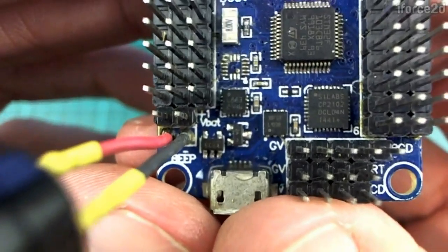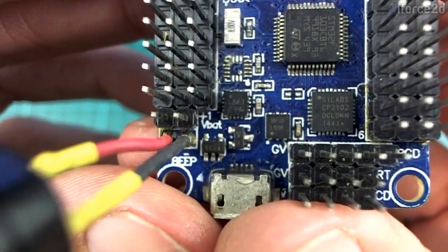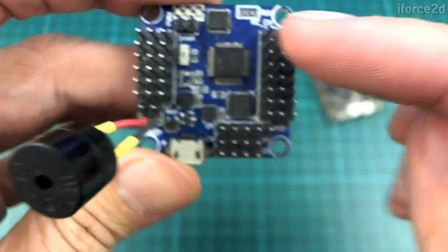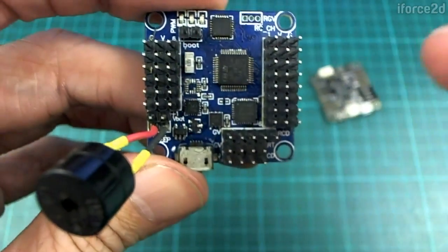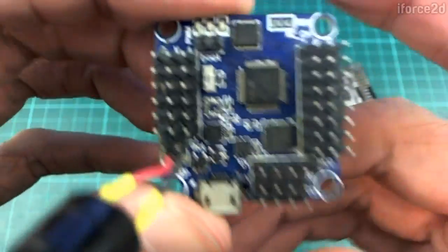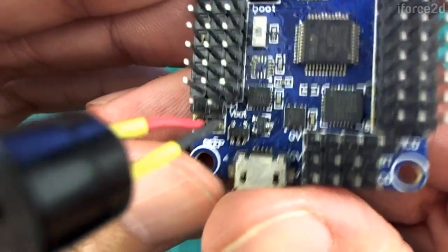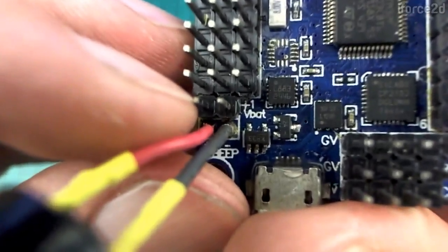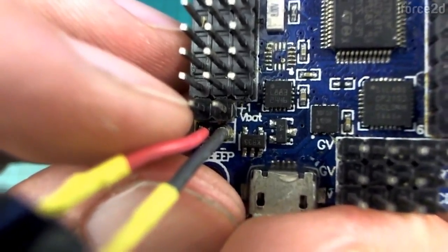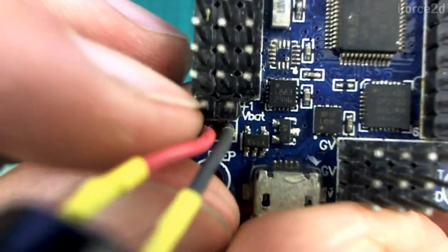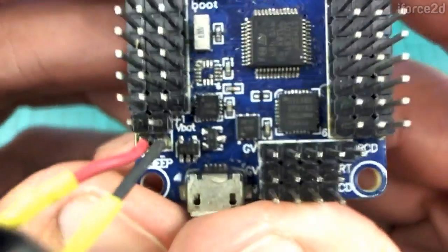And you need to make sure that you get this exactly right. You need to double check and triple check this connection before you make it, because this is all running at 5 volts, but if you connect, say, 16 volts into the wrong place, you'll fry some of these components, and you might have to buy a new flight controller, which is not fun. So we can see that the one on the right is labeled plus, so that's where the positive terminal of the battery has to go in, and that means that the one on the outside is going to be the negative terminal of the battery.